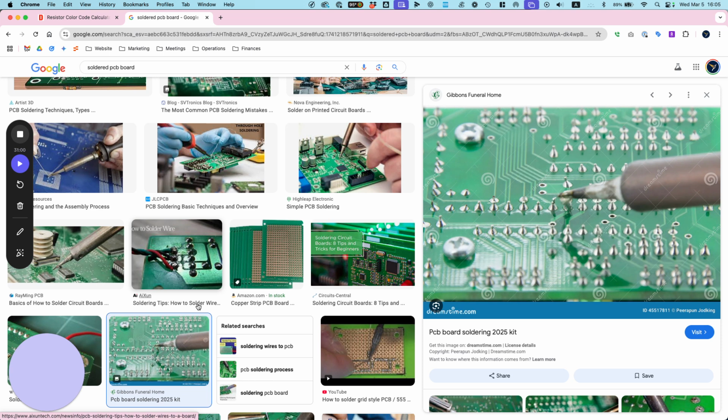Now, is that when you normally would clip it after you got a good solder? Yeah, you can clip it at this point, but normally I don't do it until I have all the neighboring components on, because as you're soldering, you might melt that component, or you might reflow that component. So I want to make sure I'm out of that area before I clip. So I'm not going to clip right now. I'm going to put the next LED component in, and then I'm going to clip.